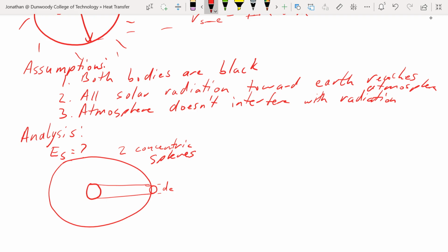I'm going to do this bit from here. So the emission from the Sun is that emissive power times pi, which is a solid angle here, d_S squared, and that's going to be what we receive over at 4 pi times the radius from the Sun to the Earth, this bit, minus d_E over 2 squared times that heat flux we'd measured.